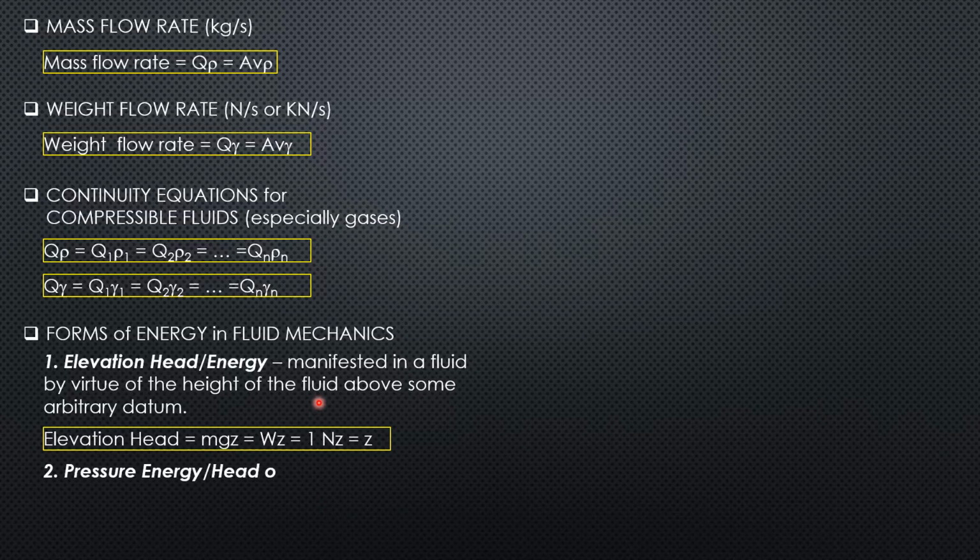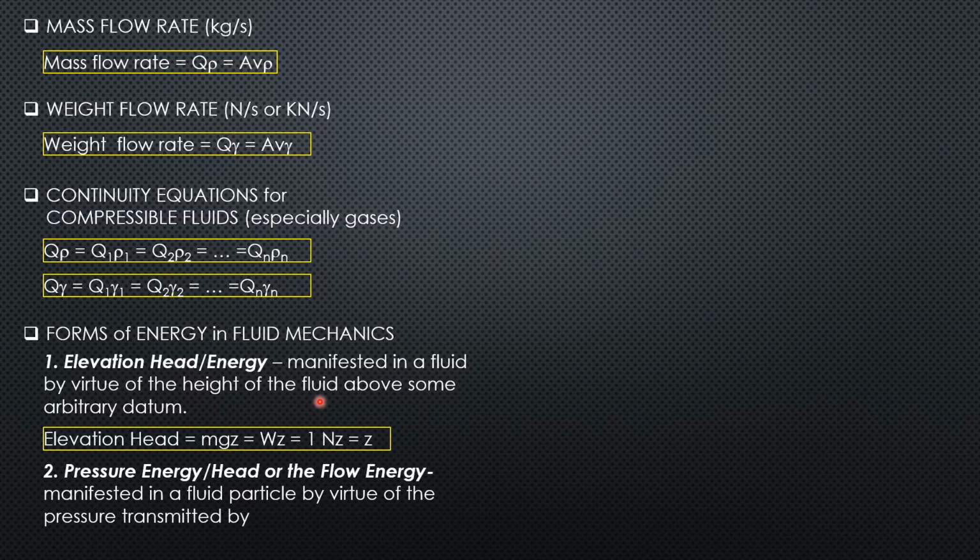Next is pressure head or pressure energy, or the flow energy, manifested in a fluid by virtue of the pressure transmitted by the surrounding particles to the other particles. So this is defined by pressure over specific weight. And that should also be in meter.